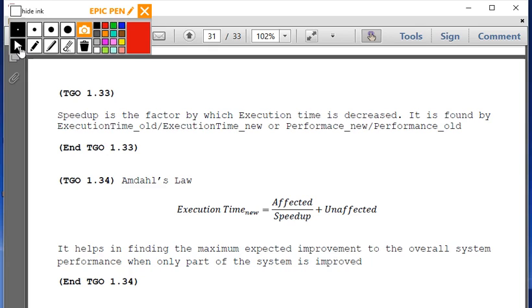Well, okay, so I've executed the instruction. First thing, I've decoded it. I've now executed. So now I have a bunch of stuff that I have out of the ALU. So what's my next step? Store. So these are the last 2 stages. I either store to data memory or write back to the local copies of the.